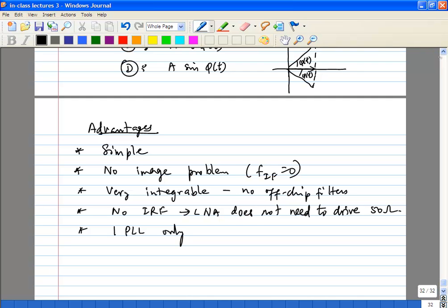I can't think off the top of my head. I can't think of anything else. Non-linearity, why? Because interferers are there, and the amplifier is non-linear. No, but your LNA better be quite linear. I don't think, at the signal levels we are talking about at the LNA, it should be a problem, because we are talking about microvolts, tens of microvolts.